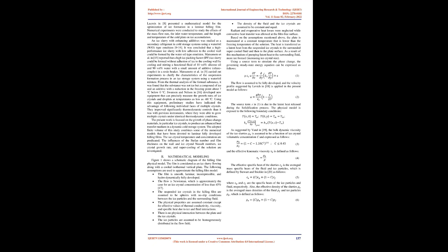Cliché and Lacroix in [8] presented a mathematical model for the optimization of ice formation in a laminar falling film. Numerical experiments were conducted to study the effects of the mass flow rate, the inlet water temperature, and the length and temperature of the cold plate on ice accumulation.